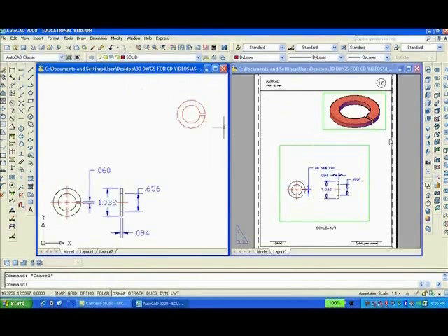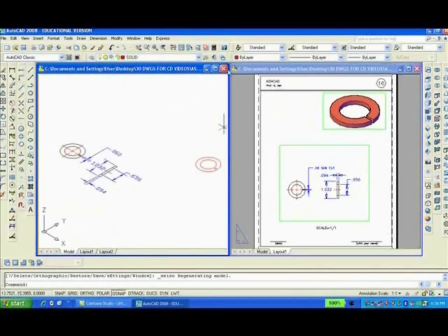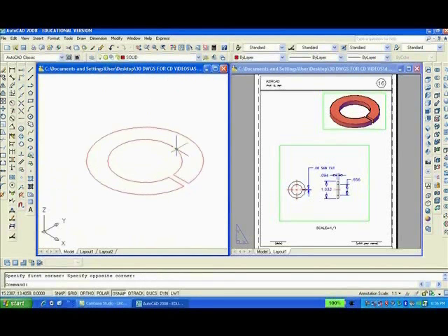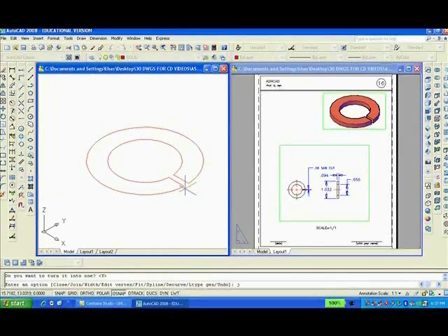And we're able to go into southeast isometric mode, pan and zoom to see it better. Now I think what we have to do is polyline edit, PE, enter. Do I want to make that a polyline? I say yes. Then I join, J, enter, and make the whole thing one. Now I want to enter twice, I guess.